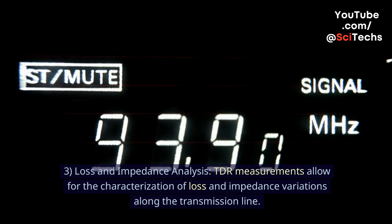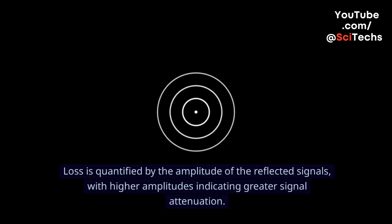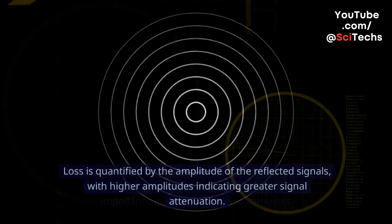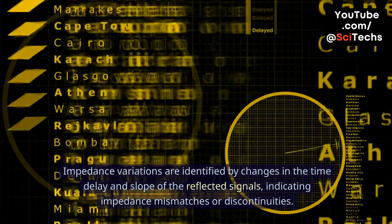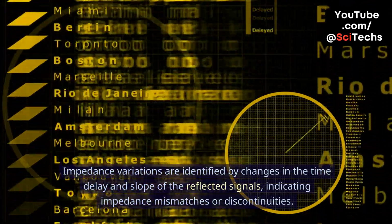3. Loss and impedance analysis. TDR measurements allow for the characterization of loss and impedance variations along the transmission line. Loss is quantified by the amplitude of the reflected signals, with higher amplitudes indicating greater signal attenuation. Impedance variations are identified by changes in the time delay and slope of the reflected signals, indicating impedance mismatches or